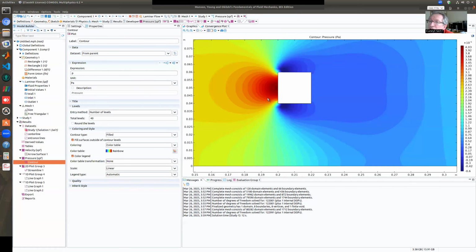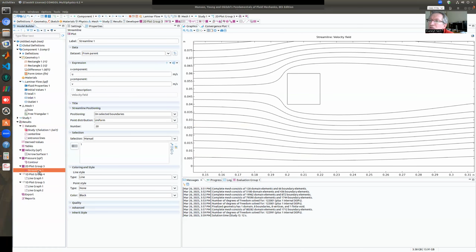And then that speed, let's go back to the pressure contour, increases as the flow goes over these corners. So as it speeds up, its pressure drops. And then here I have the minimum pressure locations, right? And then at the backside, pressure is almost constant, right? So if I just see the streamlines, the streamlines are like this. So we have a wake region, right? We have a wake region.